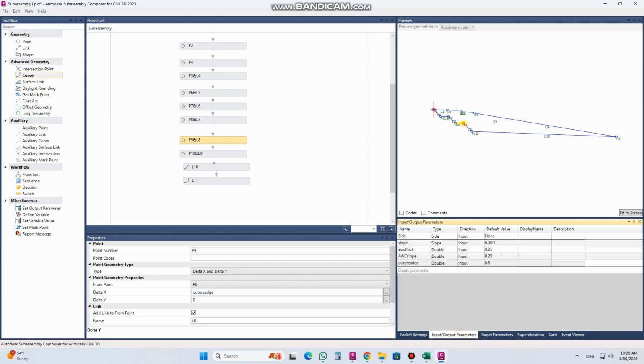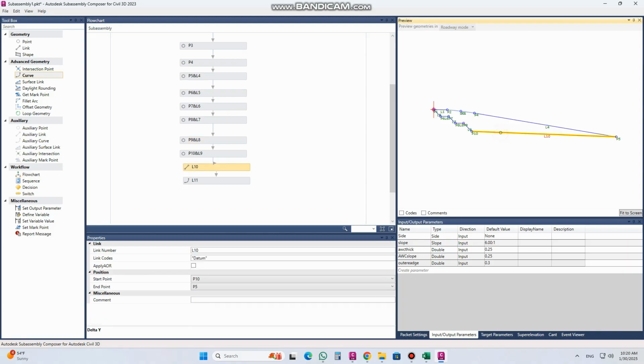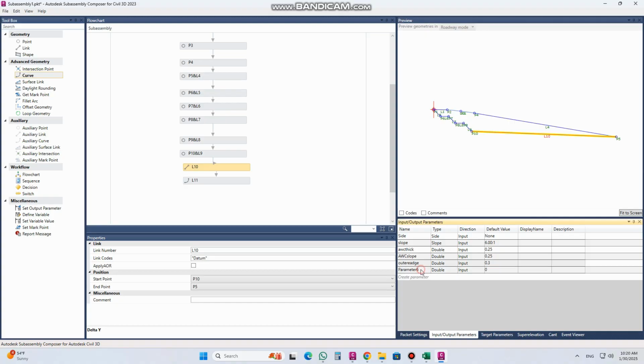We have now the super elevation for this side. Put super elevation for this length below, so it will follow the super elevation as per the super elevation of the main road, it will follow the same one. So for this, create super elevation in the type, and in the remain automatically super elevation appears. From here you can select the side, which side is better, you put none.